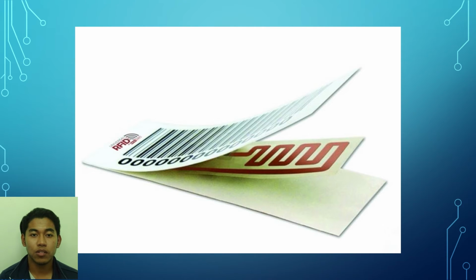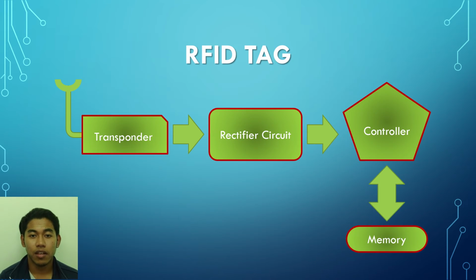Let's see what the basic components inside this RFID tag are. The first component you will see inside the RFID tag is a transponder, which receives the radio waves coming from the reader and sends the feedback signal back to the reader. As the passive tag does not have its own power supply, it relies on the radio waves coming from the reader. It gets the energy from those radio waves. Using a rectifier circuit, the energy coming from the radio wave is stored across a capacitor. This energy is used as a supply for the controller as well as the memory element inside this RFID tag.